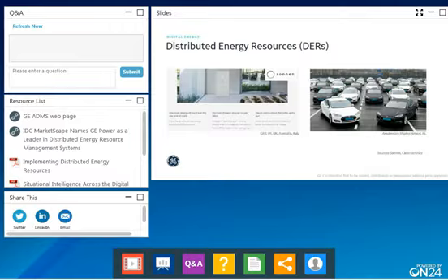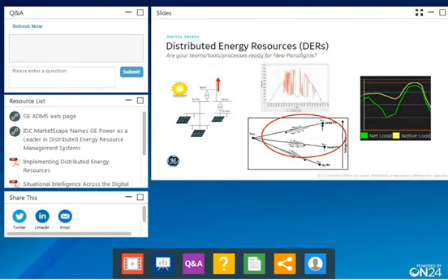So what are the challenges that this causes to the grid? Distributed energy resources essentially challenge all the good old power system engineering paradigms that we used to build our grids upon. On the left, obviously power flow goes down from transmission to distribution. Well, not anymore. Now you've got backfeed. At the bottom center, voltage profile is such that voltage decreases alongside the feeder. Well, no longer, and you can now have a voltage profile that actually increases.